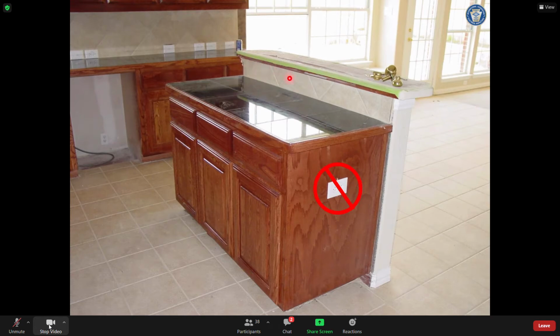Now under the 2020 code, 2021 IRC, we're going to do what? We're going to just simply get a square footage right here, which would probably call for 2 receptacles as well. And that language talking about the physically impaired or if you have backsplashes, you can't have it under the countertop. That language is not there in the 2020 code and the 2021 code.